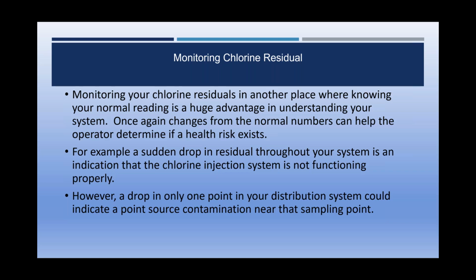And in one of the systems I worked on, we had a big panic because they found lead in one of the samples at one of the houses. Now the system had never had a problem with lead before. None of the other sample points had lead, but there was a big panic because of course lead's very toxic, particularly for children. But it turned out that because it was only at one point, we knew that the whole system was not contaminated.